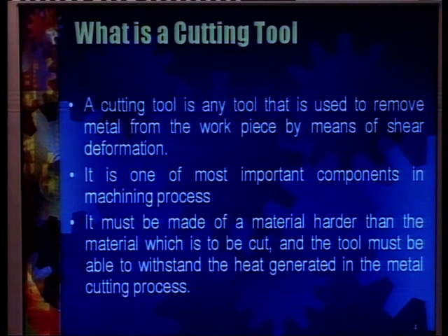So, to avoid these things, the two things, that the material should be harder and it should be able to withstand the elevated temperature, or it should have hot hardness, are very important.